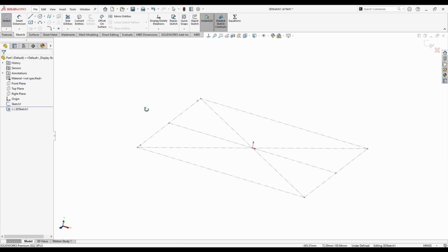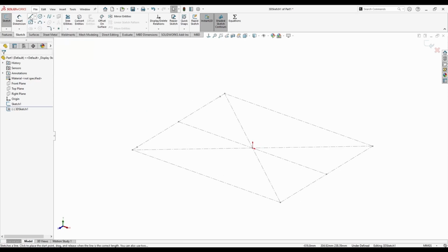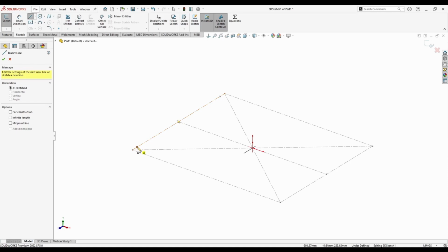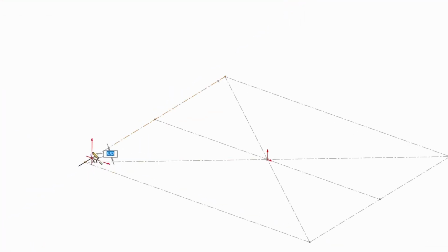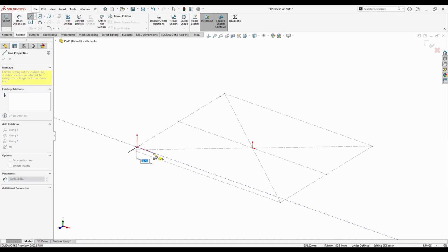When you select the command, it will select the line. If, for example, I start drawing here, 2 arrows appear, which indicate the direction or the plane, basically, on which you are drawing. As you can see in these small letters, it says XY plane, but the plane is imaginary. You don't have it. When I click the tab, these arrows change direction. And now I can draw in the YZ plane. I'll click the tab once more, and this is now the XZ plane.